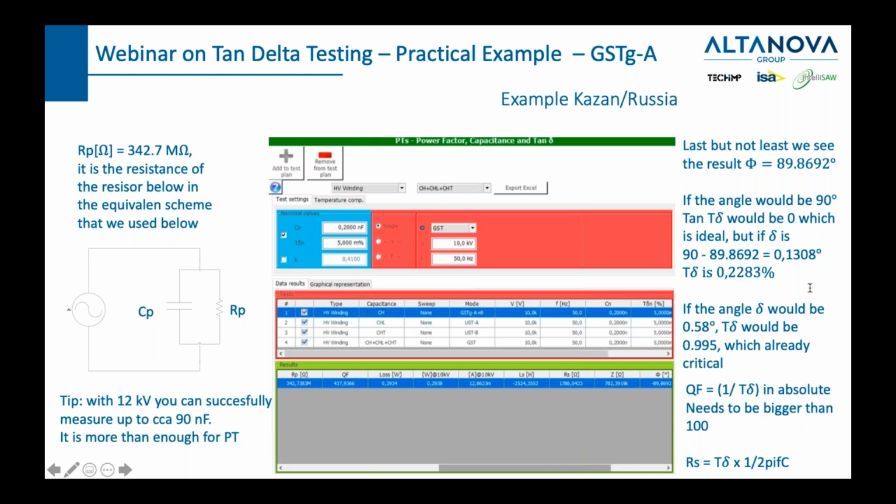If you have 11 kV cables and a certain amount of picocoulombs or millivolts, then it might not be a big problem. But if you have that same amount of millivolts on a 220 kV cable, it can soon create a problem because of the bigger stress.